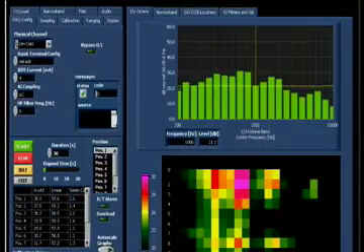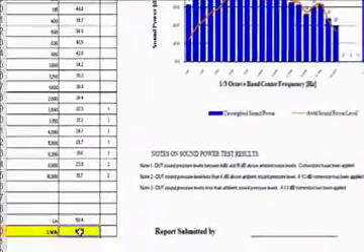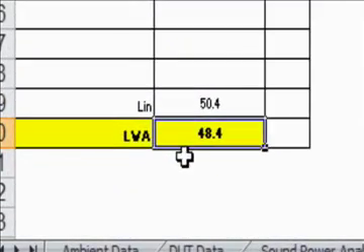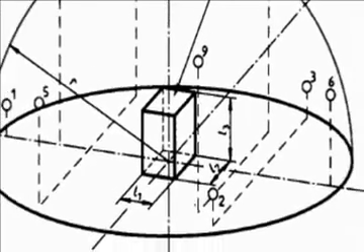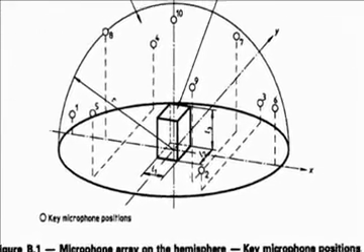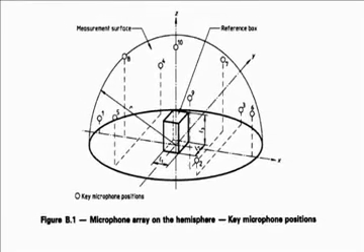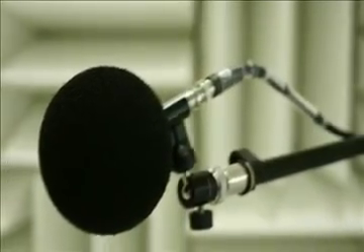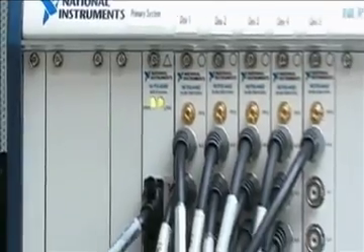The Nelson Acoustics Trident software is a tool we use for taking these measurements. The Trident software measures the sound pressure levels and exports the data so the necessary calculations to give us the end result as a sound power level can be performed. In the chamber, we place an array of brass microphones that envelope the product and measure the sound pressure levels over a predefined surface area. These brass microphones are attached to cables that lead out of the chamber to our National Instruments data acquisition system.